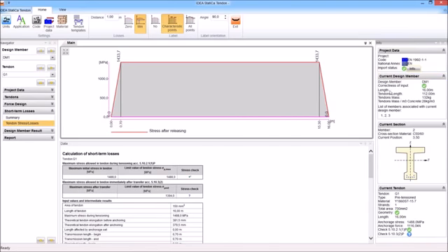The program tells us that the length of the beam is 16 meters, tendon length is 112, tendon mass together 132, and tendon mass per cubic meter is 28 kilograms of tendons per cubic meter. And also some other useful information in these windows about the current tendon and so on.